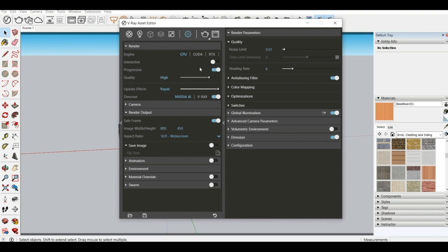Now these little settings, you'll have to practice the use of these settings, as every scene requires a different set of settings. Like if you have made a scene with the settings that I tell you, and you want to add even a single light, that can change the whole render of the model. Like it may increase the brightness or highly increase the exposure, so you have to keep that in mind and practice for that.